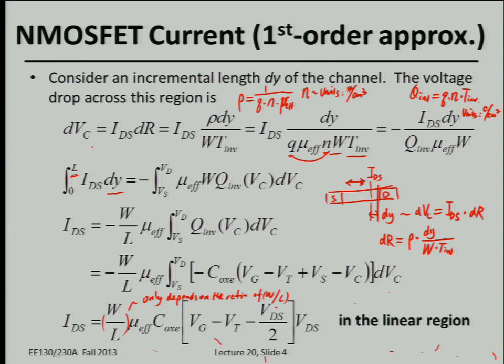Okay, and also pay attention here: once you use the capacitance value to calculate the current through a MOSFET, you should use the areal capacitance, right? That's like farad per centimeter squared, right? Once you also use the same quantity to calculate the inversion charge concentration, the same thing applies here, okay?